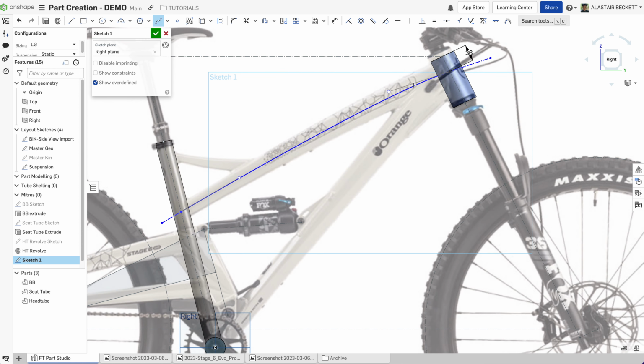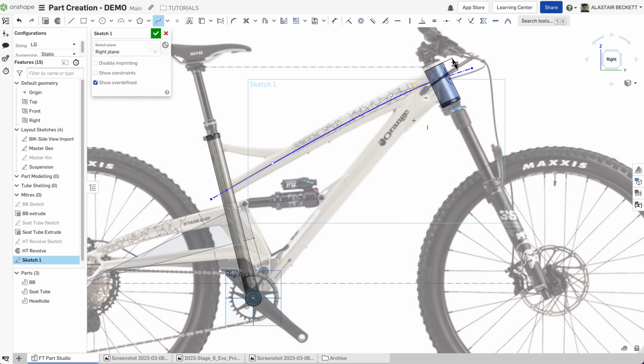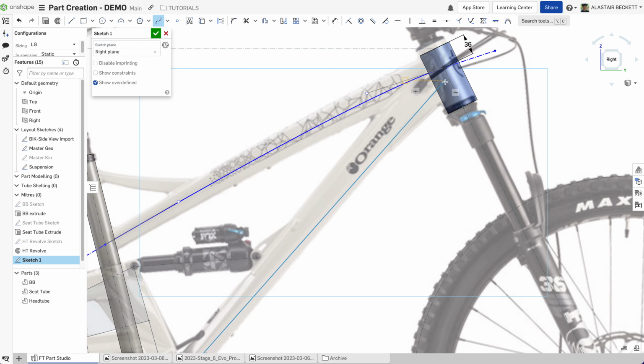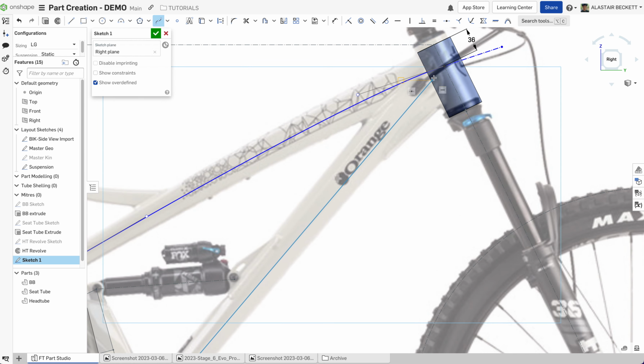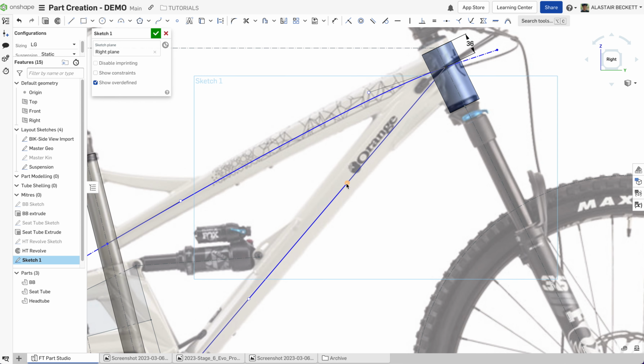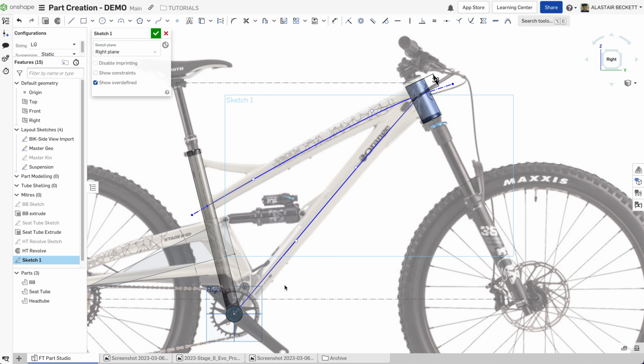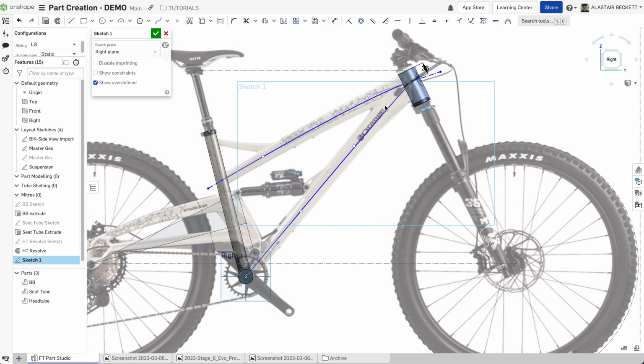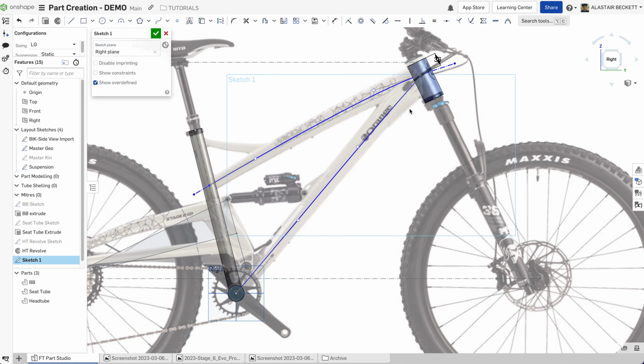We'll stick another curve in. These can all be in the same sketch because they're really just a guide. So we're going to start. Down tube looks like it starts roughly down here where the BB is, and if we were to follow this straight line, it looks like it goes to pretty much where the top tube joins. So let's go with that as an example. We'll give it a slight bow up here, and that looks pretty good. So we don't really need to do too much more on that down tube from where we are.